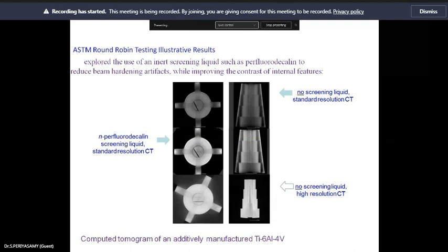Here the scanning strategies are given. The different scanning strategies affect the thermal history during the SLM process and considerably alter the material properties, including density, thermal and residual stresses. Even the same thing will be captured continuously. You can capture the image using an infrared camera at high speed.